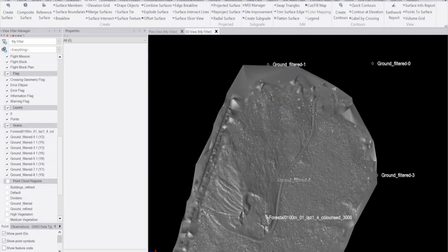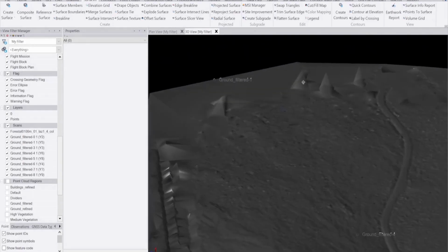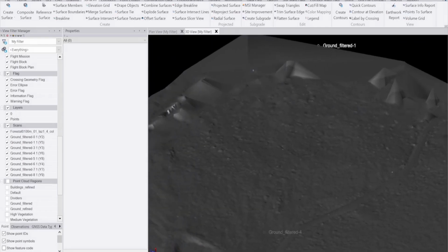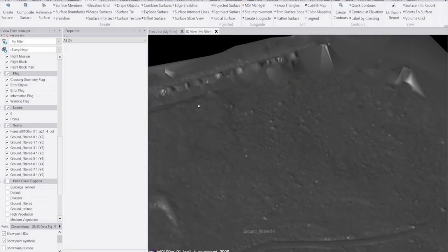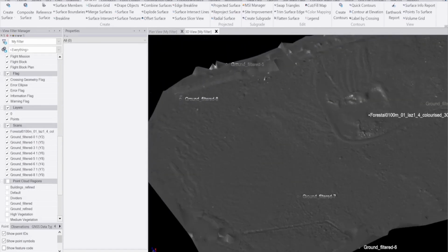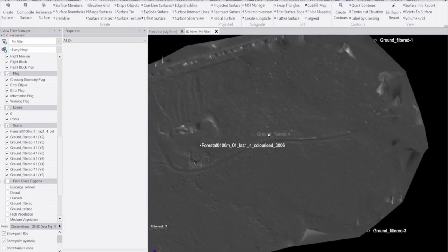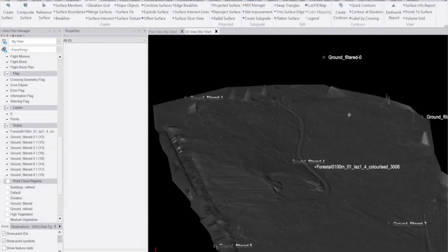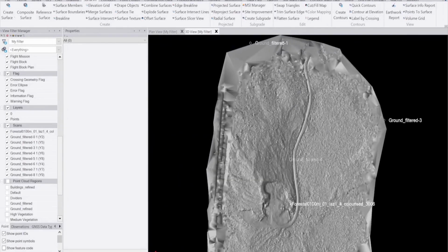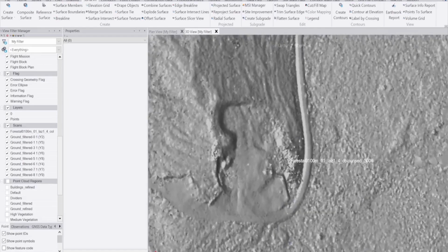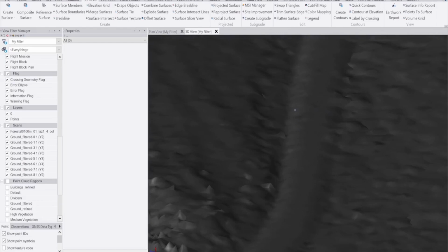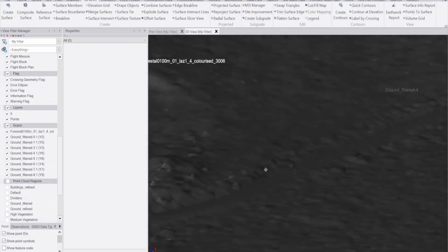These points further out are very sparse, which is why some of these points were quite high, only capturing trees and nothing underneath the canopy. What I'll do shortly is trim the triangulation so we don't have any of that information in the final output. One thing I do want to do is draw the centre line of this road coming in, and I'm just going to make the edges of the road a bit more pronounced.